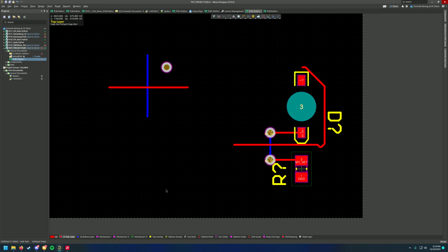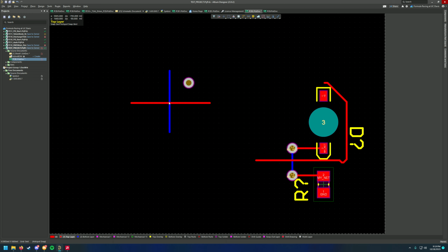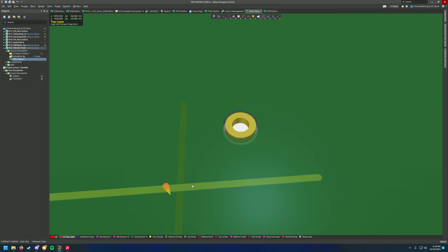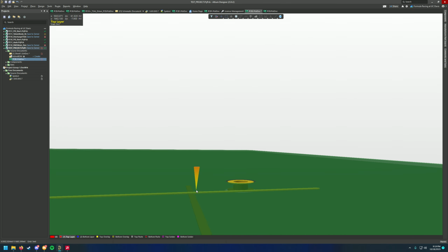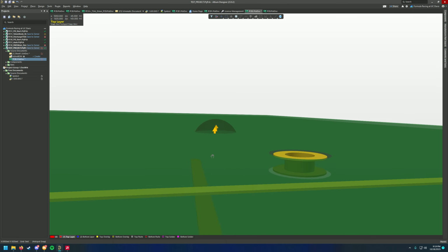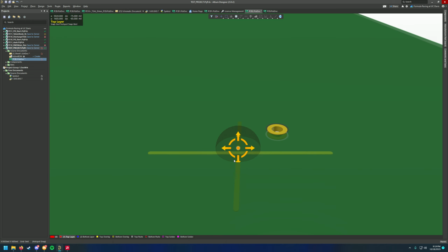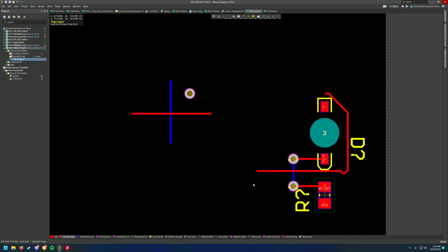This board right now has 2 layers, just the top layer and the bottom layer. You can have more. Your layers will all show up down here at the bottom. It's probably hard to read, but we have top layer and bottom layer. These are copper layers, so these are actual metal, which is going to be deposited on the PCB for connecting together circuit components.